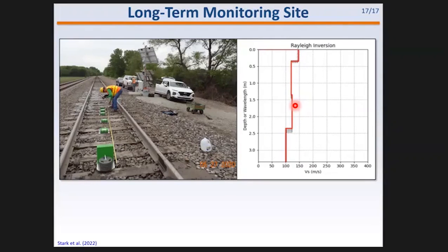Okay, first, I want to correct: we didn't assume. We ran some LS-DYNA numerical analyses to look at the depth of influence under the applied loads that we had measured at the site. The analysis shows us about 8 inches. And that's closer to the control site than the fouled site for sure, but still roughly the same.